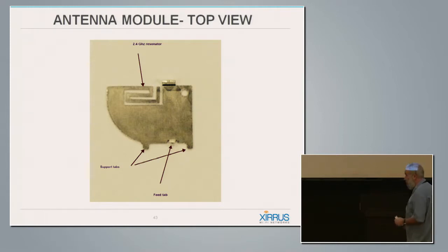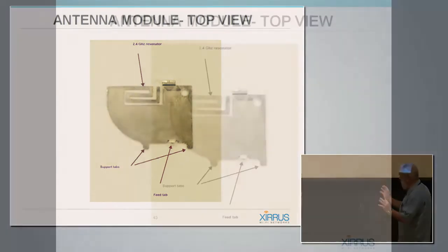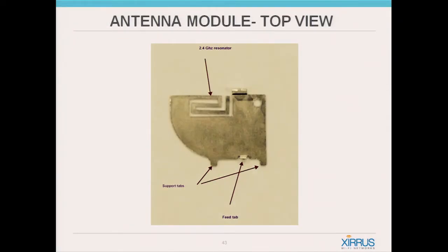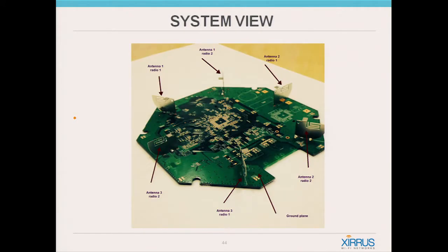The beauty of that design is it's got some directionality to it. And as I'll mention later, it helps me to achieve the same isolation numbers that I've been achieving with our other products. So what happens here is that in this case, it's a 3x3. So imagine that you can see 6 monopole antennas, but as I mentioned earlier, I'm putting it against the wall, so the energy is splashing down and to the side. Unlike the dipole, the energy is pushed down.